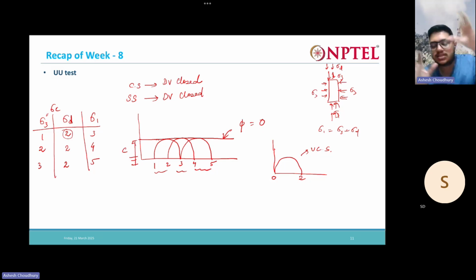The extra load that comes from my confining stress is actually taken by the pore water. That load is transferred to the pore water, and my soil is failing at the same load of 2 because it can take only a specified load itself. It cannot take more load because we are not allowing drainage, volume change, or consolidation.